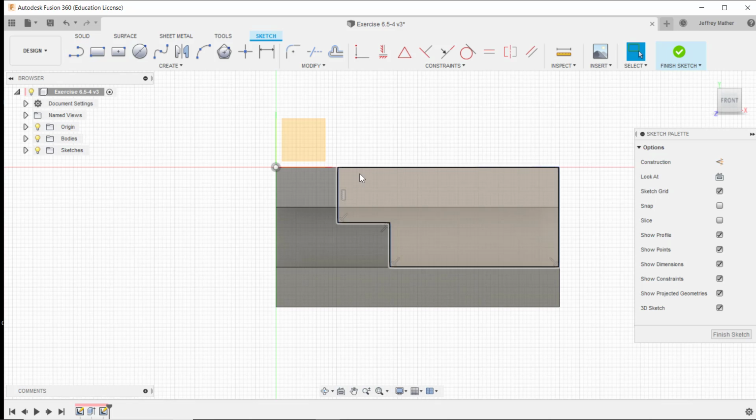Alright, if I try to drag these lines, the first step I said was to put in a dimension so that you have a sense of scale. So we have a sense of scale of our object now. And then the second, and actually this might be really the most important tip, when the lines don't change color to black, one of the things you might want to do is drag an endpoint. If I drag the endpoint, I see that this line isn't staying horizontal and it's supposed to be horizontal.